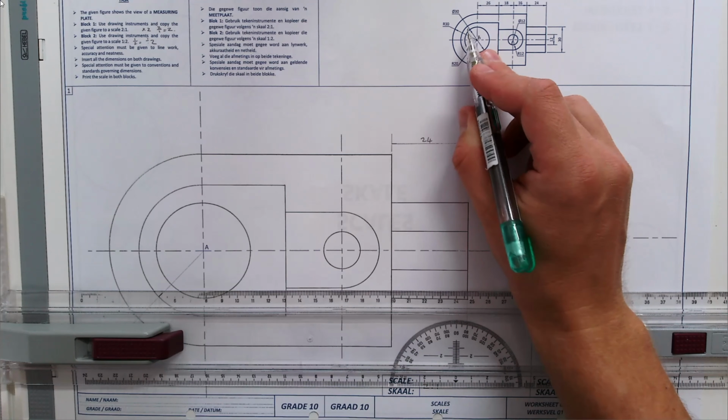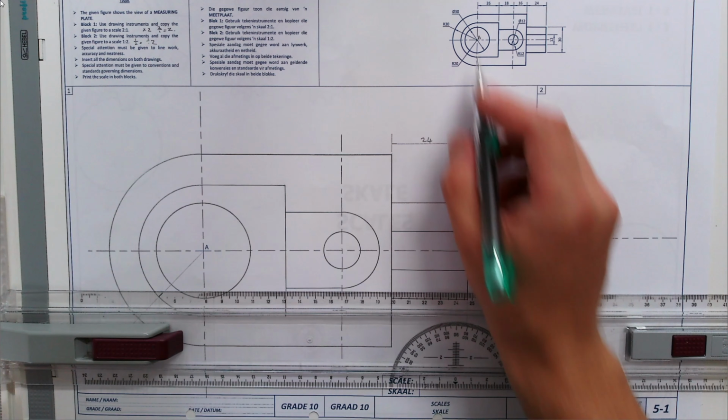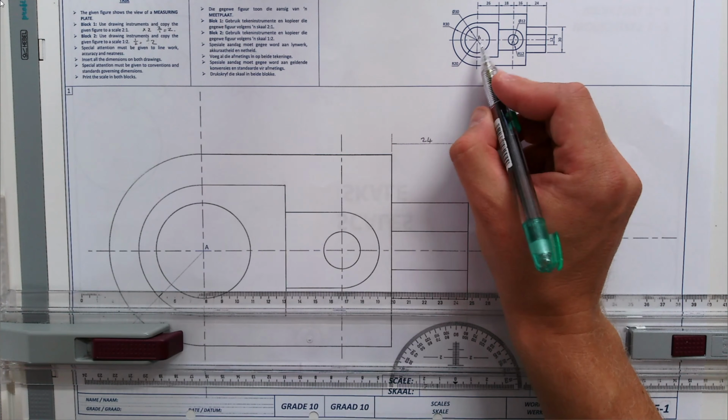Now I can put in that half circle. That half circle has a radius of 20. 20 divided by 2 is 10. So radius 10, diameter wise, it's going to be diameter 20. So you can once again use your circle stencil if you want to. You can put it in the middle like so and only draw in a half circle, but I'll use my compass for this.